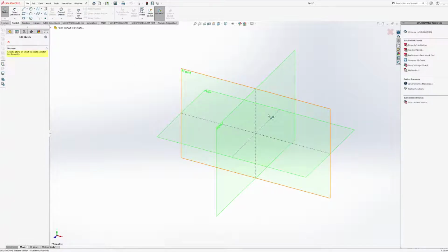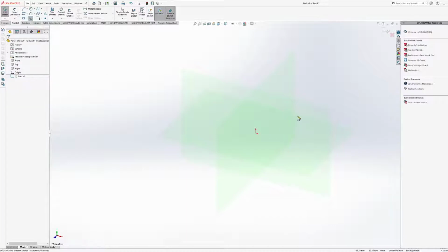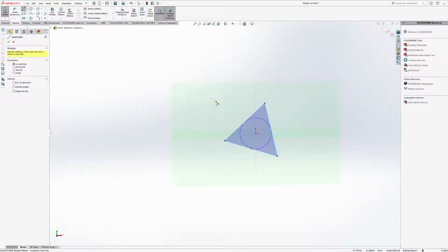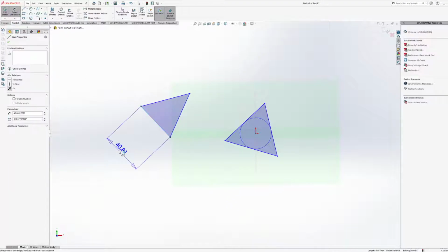I haven't played around with polygon that much, so honestly that might do it, maybe? Holy cow, you can make something like that as well, I think. Can you? I have actually no idea. Ha, that's awesome. So you can make super easy equilateral triangles as well. Today I learned. The other way of doing this would literally just be using the line tool, and then you would just create a 3-sided object, and then you can smart dimension everything appropriately.